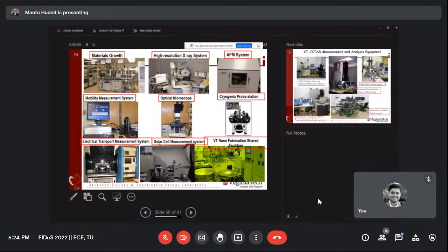The stage can handle that. Then we did some cool stuff: we also mounted a simulated solar light on top of this window, which means we can shine light during the measurement, so light-induced measurements are possible too. Another capability is high temperature: it can go up to 300 degrees C in my lab. That's the measurement setup: semiconductor parameter analyzer and solar simulator facilities.